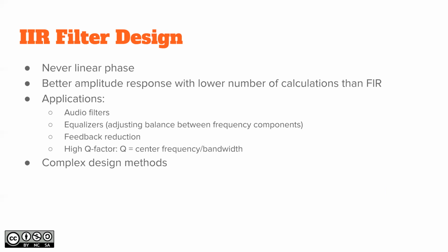Then some words about IIR filter design. Okay, first of all, IIR filters are never linear phase, never ever. But most of the applications don't care. For example, audio processing doesn't care, say, for voice or something like that. If it's communication, then you might have a need there.